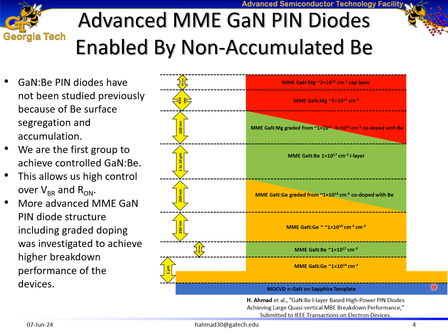Then I grew these gallium nitride pin diodes. This slide shows a layer structure diagram of my devices, where first I sandwiched a beryllium doped gallium nitride film inside the n-type layer, and the beryllium doping was 1 x 10^17 per centimeter cube. And then I grew beryllium doped gallium nitride eye layers with eye layer thicknesses of 1, 2, 5, and 10 micrometers. And I kept the transition layer between the n-type and the eye layer to be a graded junction for improved breakdown performance. Later, I deposited a magnesium doped gallium nitride top layer with a cap layer as well.